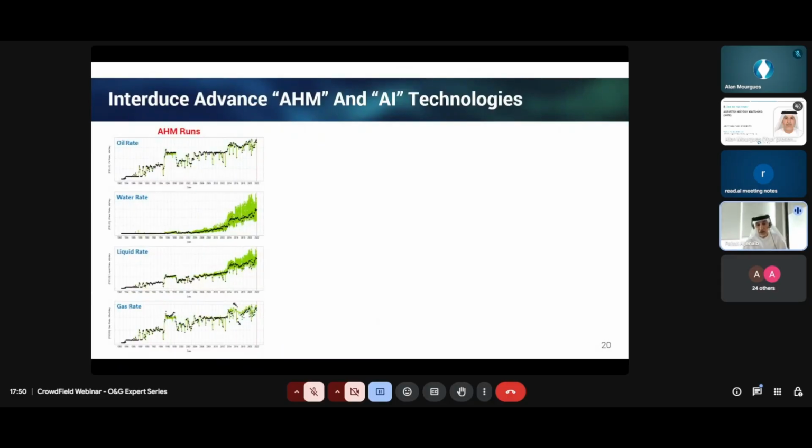Okay, now I come close to my finals. Let's assume I've done my homework. I run thousands of runs. I'm getting the cloud around the actual data. I'm using oil rate as the main driver, or let's say control parameter, so I'm honoring oil rate. Water is up and down. Liquid, gas, also there are many runs up and down, but they are so close. So I get a lot of results, and I don't know now how to select or come up with the best solutions.